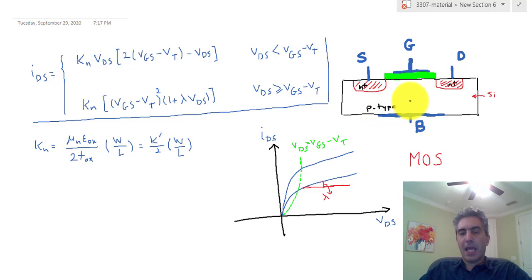In the case of an NMOS, or n-type MOS transistor, the substrate is doped lightly p-type with boron, and then there are two areas of highly n-type doped regions that behave very much like conductors. In between the two, the p-type creates a barrier, and this is called the channel.